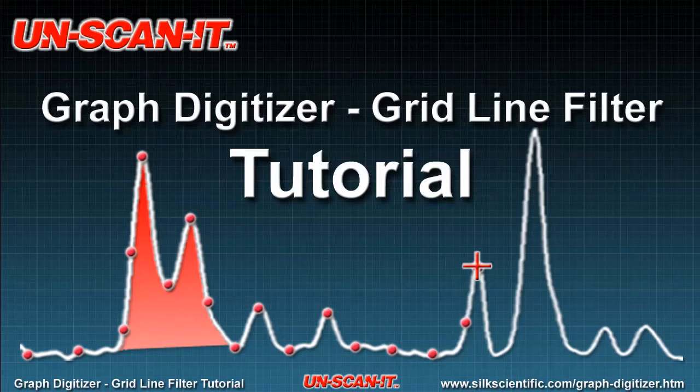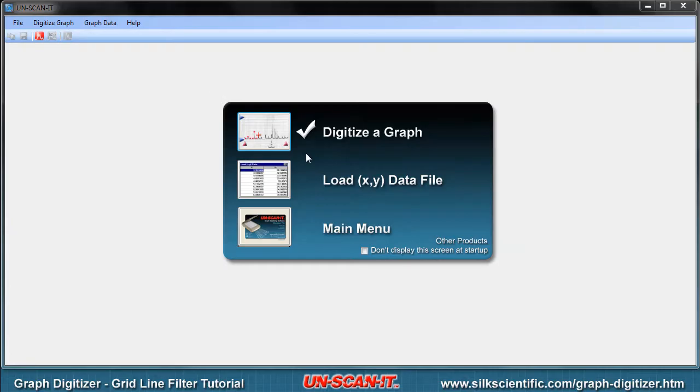Welcome to the Graph Digitizer grid-line filter tutorial for the UN-SCAN-IT software. This tutorial will step you through the automatic graph digitizing process used to filter and ignore grid lines using the UN-SCAN-IT software. A startup screen will appear when the software is opened, and a pop-up menu will allow you to digitize a graph. This option can also be selected from the main Digitize menu or the Digitize toolbar.